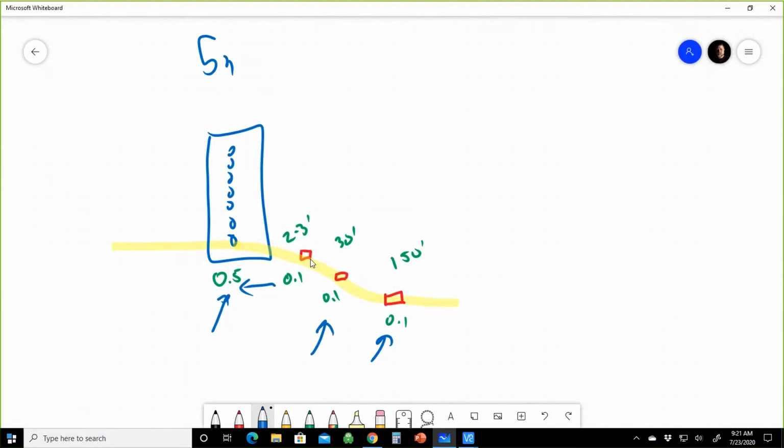We're starting to see some companies actually increase their patch panel loss to assume that there's a pigtail splice nearby, particularly for some of these pre-terminated panels. So at 5 nanoseconds, that's what we see.